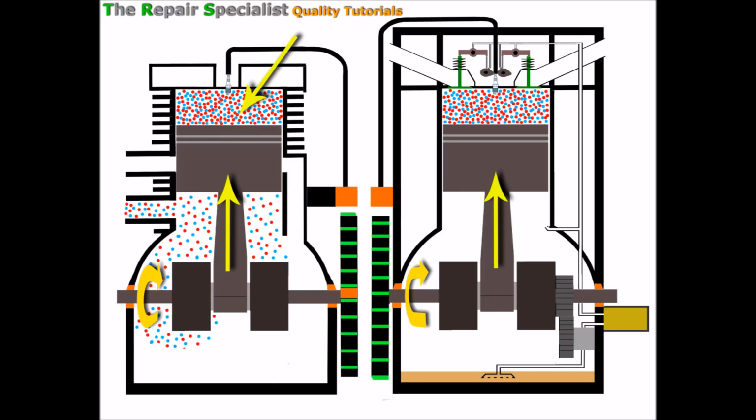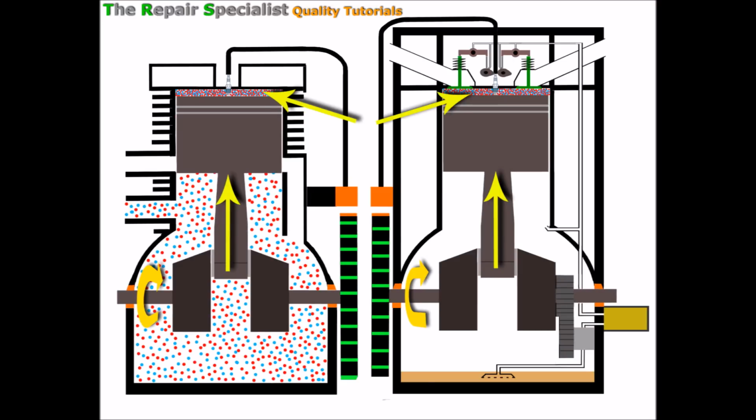So we've got the compression there, and the 4-stroke engine's achieved its compression because the inlet valve's closed there, and so is the exhaust valve, because we've got the timing on the 2 cams there that are just so to allow that to be. And again, both engines are at the same state now. They're both on the compression stroke. And if we continue now and let the crank turn, the pistons rise because the crank's now turned another 90 degrees, and now we're at top dead centre.